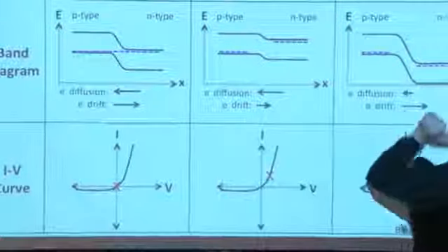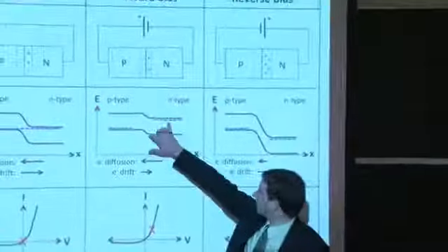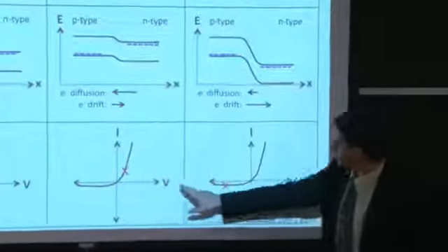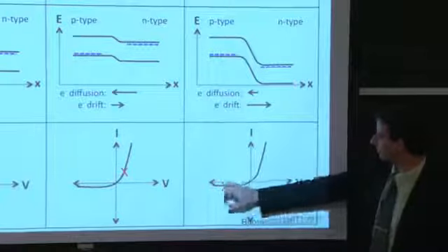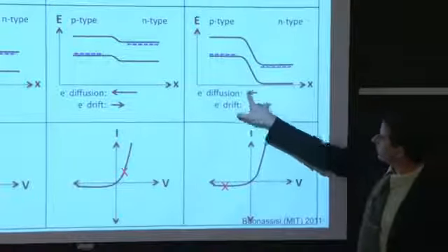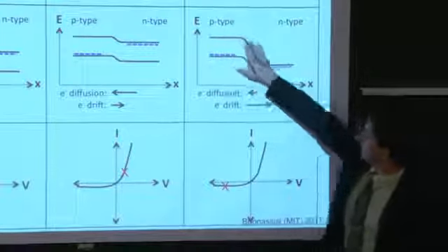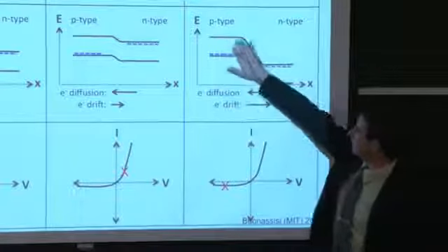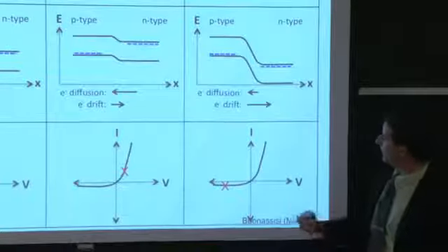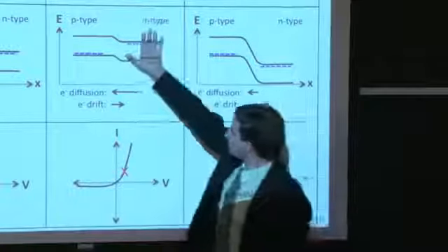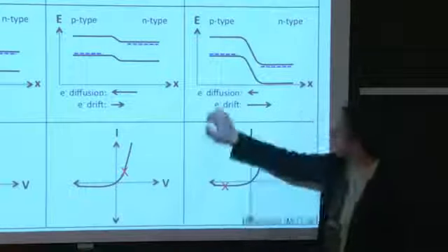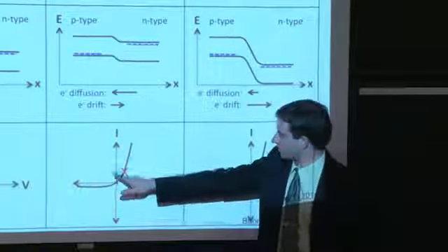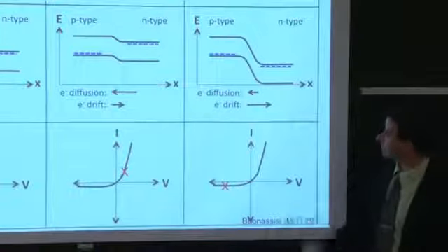When we reverse bias our device, notice the separation of the quasi-Fermi energies. Again, we have here one sign of voltage because the right side is higher than the left. And now the right side is lower than the left, so our voltage sign flips from positive to negative values. So notice the voltage, and now the current as well. The drift current will outweigh the diffusion current in this particular case because now the barrier for electrons to diffuse from the n to the p-type is very large. They'll have difficulty going from that side to that side, whereas the drift current is larger because of the larger electric field. As a result, the drift current will dominate. And so now instead of electrons flowing from n-type to p-type, which we defined as positive current, electrons are flowing from p-type to n-type in net, which we define as negative current, and that's why our current has changed signs. Over here, notice that we're in positive current territory, and over here, notice we're in negative current territory.